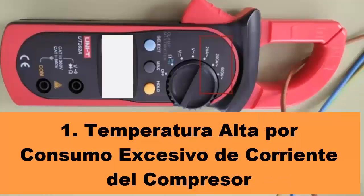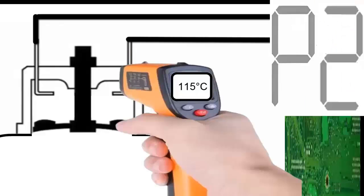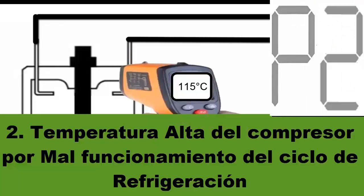Remember that other possible causes of the P2 error code may include high current in the compressor due to short circuits, wiring problems, issues with the electronic board, or low power supply voltage from the external electrical network. The P2 code may also be caused by a high compressor temperature due to excess refrigerant, a blocked capillary tube, a dirty condensing unit, or fan speed issues.